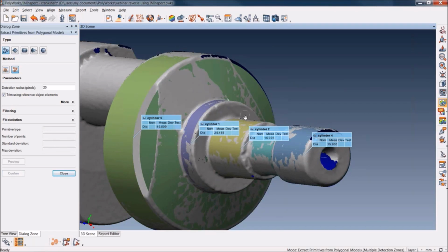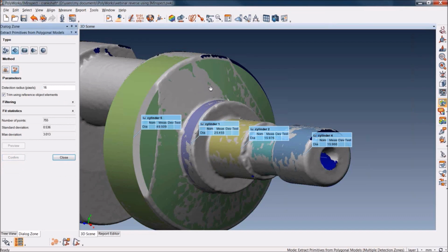and you may have to click over here. Sometimes the surface is flat. Sometimes there might be a little bit of noise inside of there. If that's the case, and what we're seeing right here is this is starting to form a cylinder, we can restrict the software to say, you know what, I want to just create a plane from these multiple selections. And instead of using the automatic, we can do that.